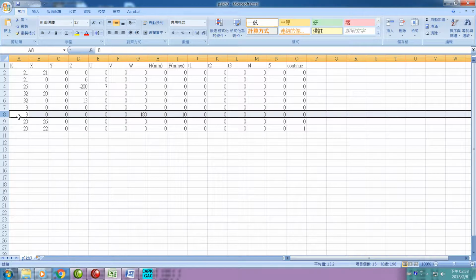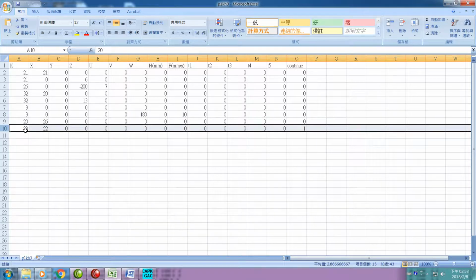After turning, the next program will be executed. How to let the next program be executed? That means water jet cutting the parts. We see this line in advance: K20 22. That means let input 22 become 1. As input 22 becomes 1, the next program will be executed.